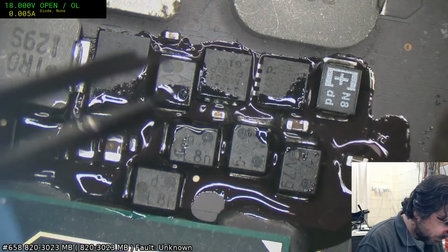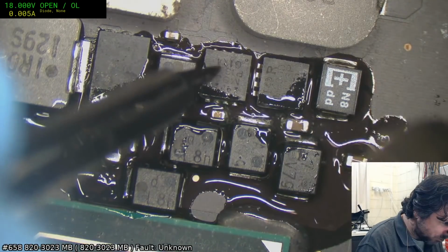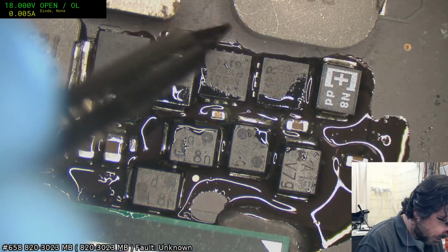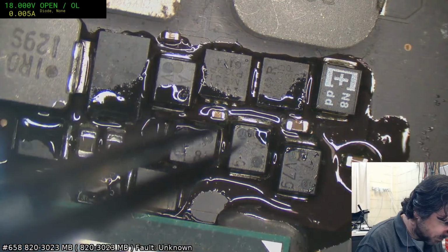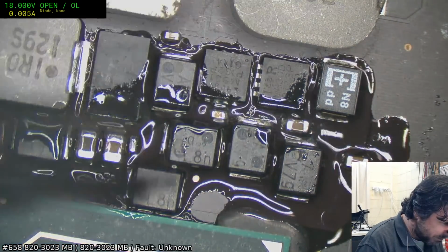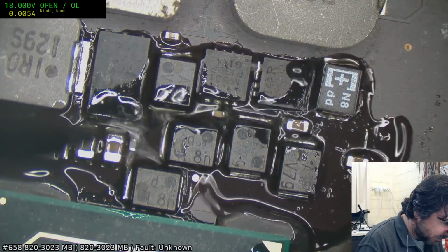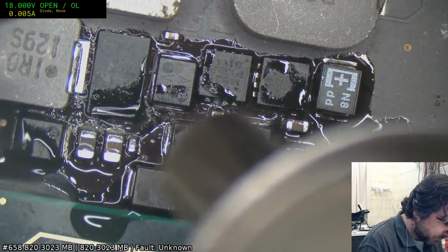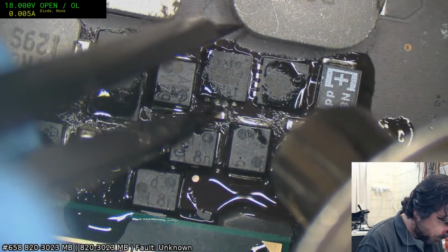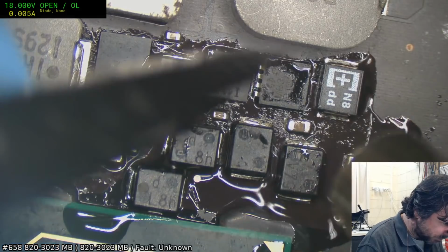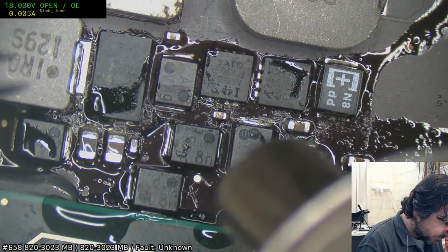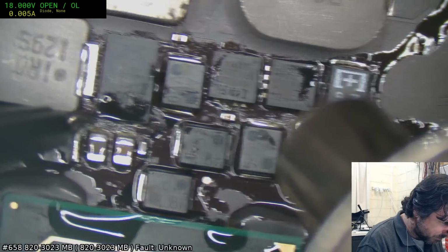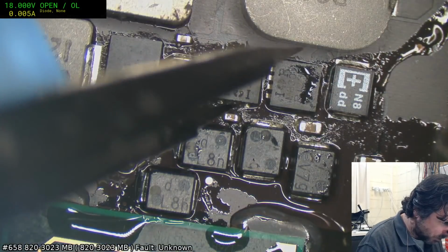That's what's happening: as the chips naturally expand and contract with the board, it's taking it out on the outer pads and just shearing them off bit by bit. I don't believe it is actually a macro scale physical flex problem. I know that's the popular opinion, but I don't believe it myself. Especially since you get the ones that seem to just die on the shelf anyway.